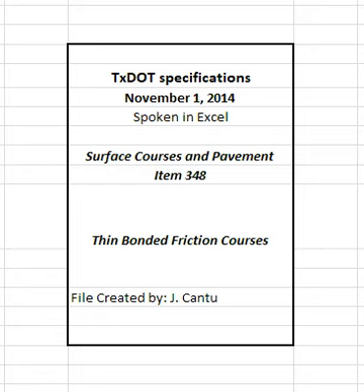3. Equipment. Provide required or necessary equipment in accordance with Item 320, Equipment for Asphalt Concrete Pavement. When AR binder is specified, equip the hot mix plant with an inline viscosity measuring device located between the blending unit and the mixing drum. Provide a means to calibrate the asphalt mass flow meter on site when a meter is used.